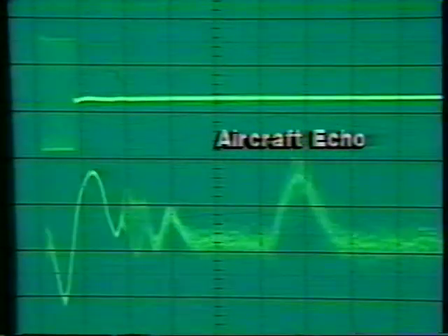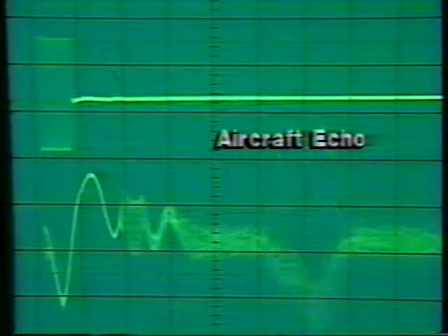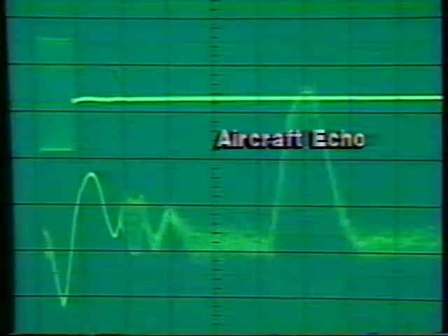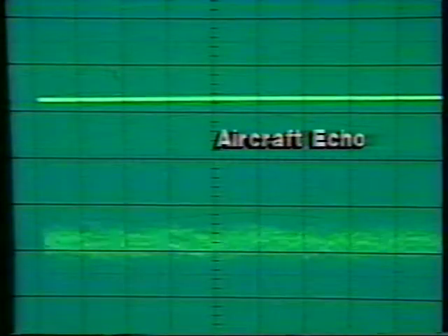There are other cases where we'll have some trouble. Aircraft interference, for example, will cause loss of data. Ground clutter is a problem. Radio interference can be a problem. And probably the one problem which will be most difficult to solve totally is what we call the side lobe problem. That is, the antenna points in a particular direction, but it has side lobes which point smaller amounts of energy in other directions.